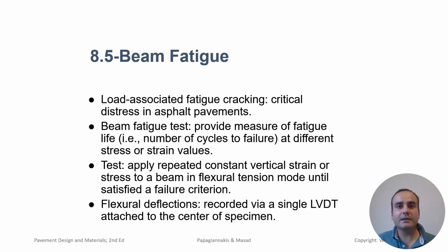The beam fatigue test evaluates the asphalt mixture's ability to resist fatigue cracking under repeated bending or flexural loads. In this test, an asphalt beam is subjected to cyclic loading until failure, helping to determine the mixture's fatigue life and performance in the field. Beam fatigue testing is essential for designing long-lasting pavements that can withstand repeated traffic loading without cracking.